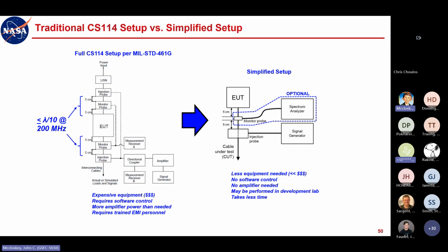So the open circuit potential that these signal generators can provide, certainly the RF signal generators that I've been using, their maximum drive capability is 120 dB microvolts RMS, or 1 volt. And so the open circuit potential is twice that, or 2 volts RMS.